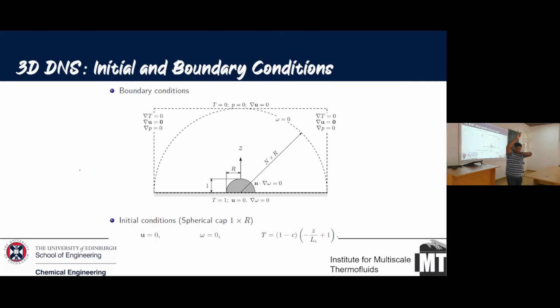So there's a lot of artificial sucking going on. If you want to make sure that you're able to make experiments, you need to have a sufficient height of the domain. We found that the typical height of the domain is 20 times the radius. Okay, so this is approximately 20 times the radius, to have more plausible results, to have better results.